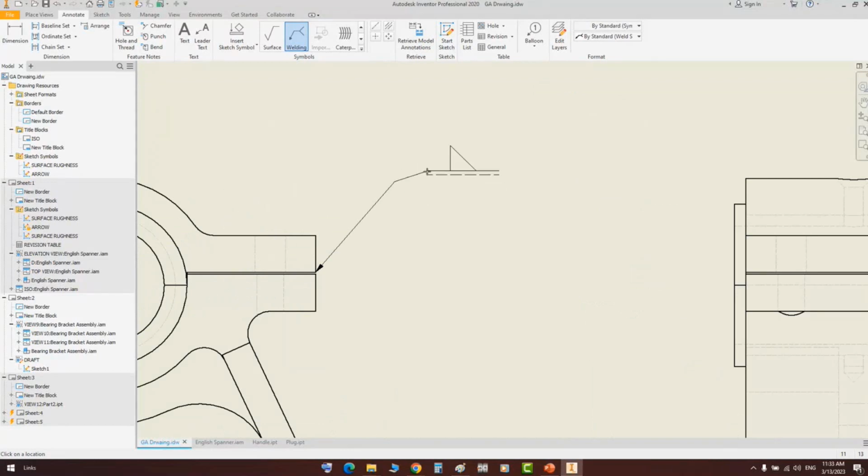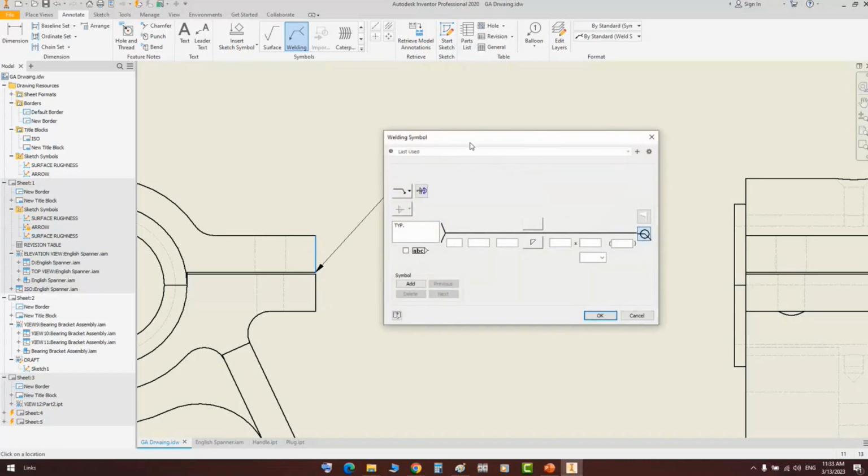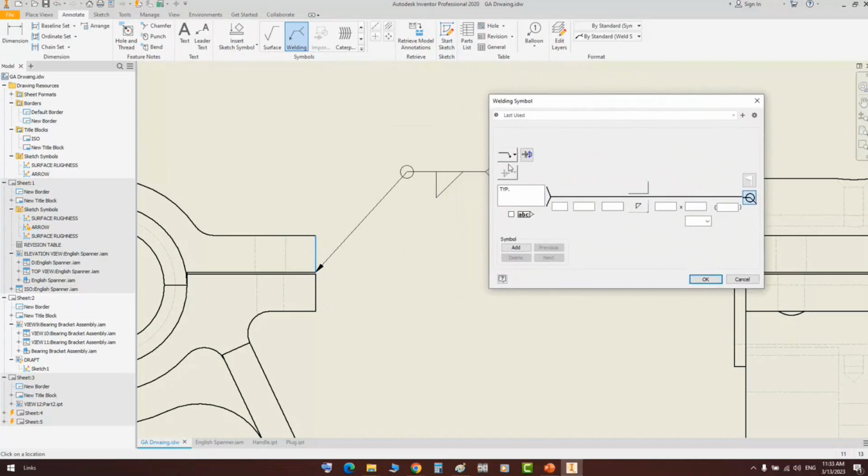So by that way, by selecting a weld, you can select the sample of weld and continue to edit the form from here. So you can select the default value. You can flip the direction of the fillet weld. You can configure this triangle direction at up. If you flip it, it will be at down. That's the default. You can make it as a circular weld. Make it a filled weld by adding a flag here, or make it a circular weld.